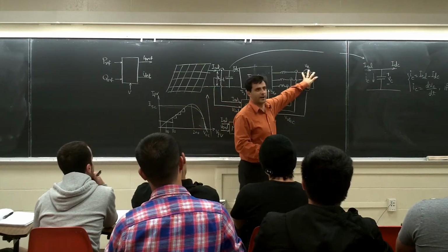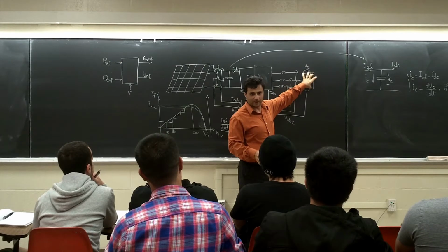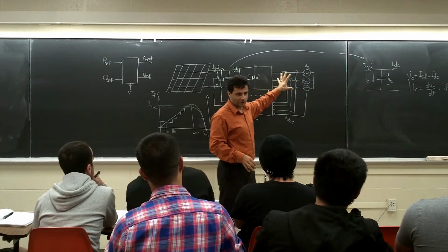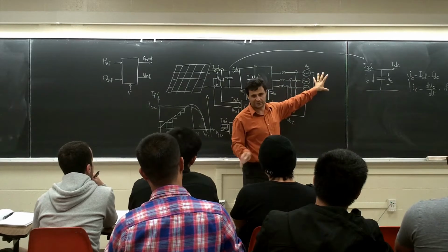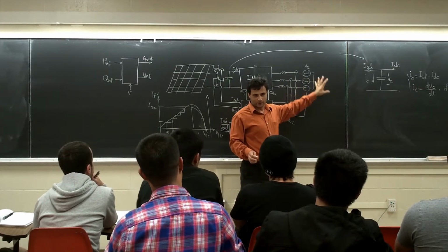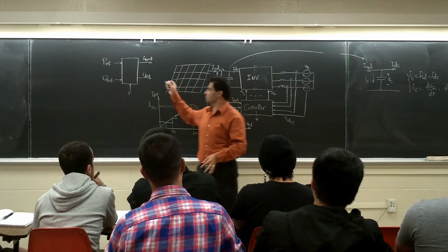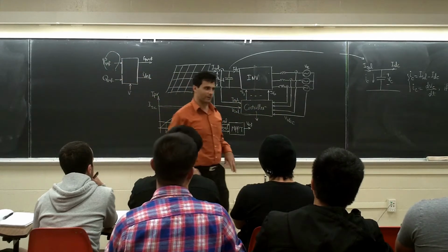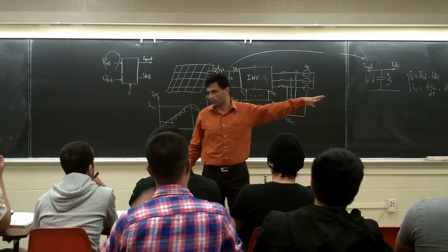Because see, the load is here. The inverter should somehow act to see a smaller load or bigger resistor, as you mentioned. So to do that, the inverter says, just tell me how much you want, I'll take care of that, right? The IDQ control we talked about, right?